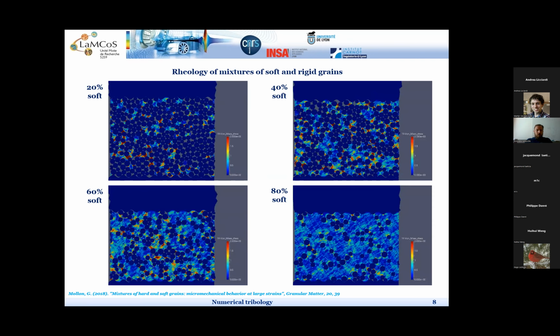So first of all, we must remind that rock surfaces are rough at all scales. It's been known for a while, and it's been, for example, documented in this famous paper by Candela in 2012, where they showed that there was some kind of continuity of the statistical laws of roughness across many decades of spatial scale, I believe 9 decades, if I'm not wrong. And this is also true, for example, at the surface of any sand grain. It's been documented as well. And this has some mechanical consequences in terms of contact mechanics.